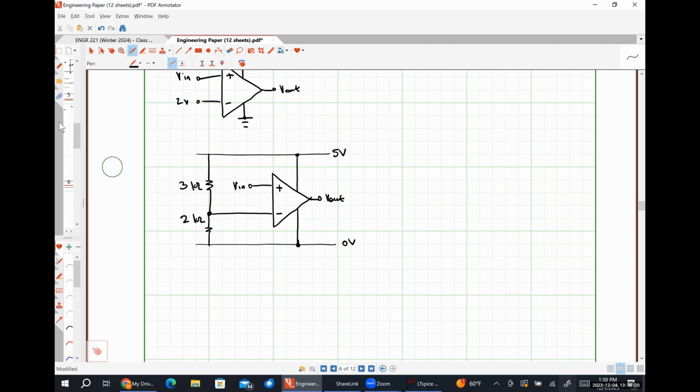Like part A. So I say that because what's your peak value of your voltage here? 1.5 volts. It's 1.5 times 12, 18. Is 18 less than VCC plus? Okay, so there's not gonna be any saturation distortion. What is negative 1.5 times 12? Negative 18. Is that more negative than negative 20 volts? It is not. No saturation distortion. So it's literally gonna be this exact graph, except where it says 1.5, make it say 18.